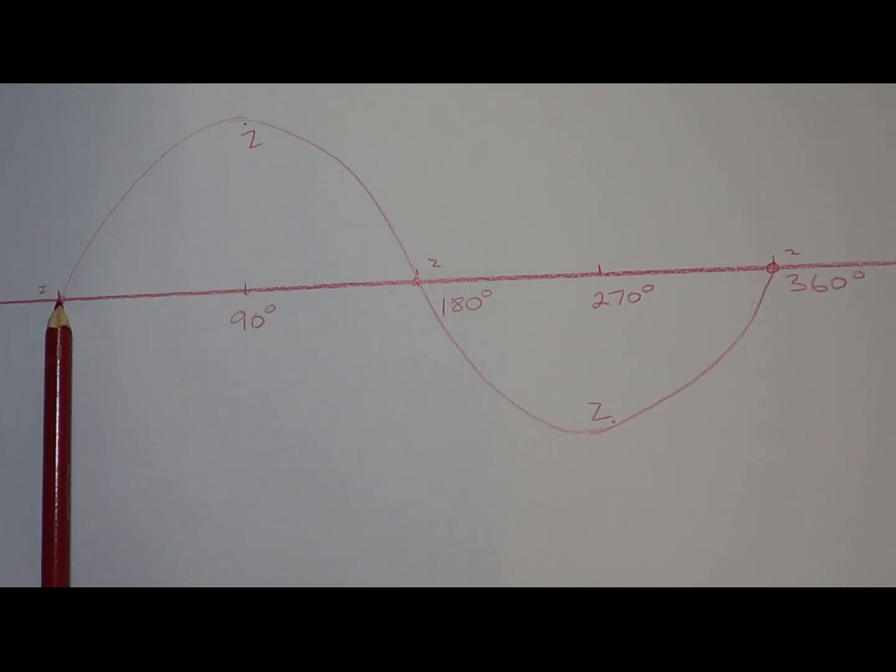All the other frequencies will not be a short circuit. So we won't have zero impedance for the other frequencies, but for the desired frequency you will. Now bear in mind that the notch is not very narrow, and they tend to be quite wide. So these sort of notches will produce a very wide notch.